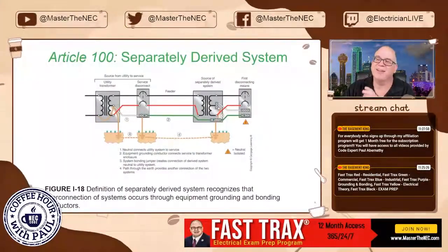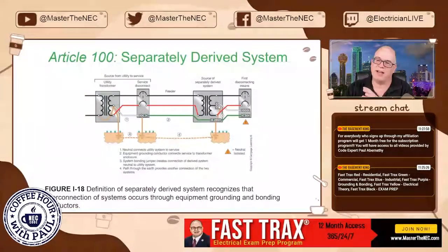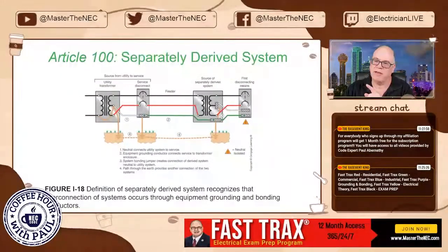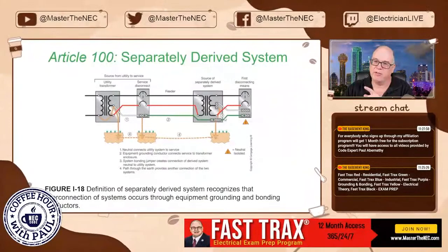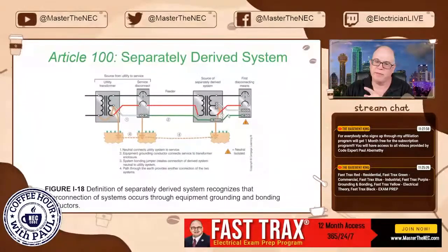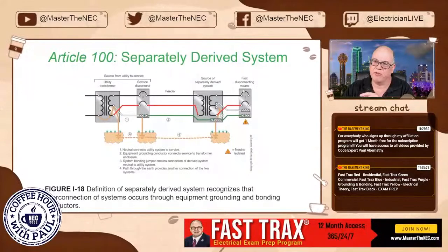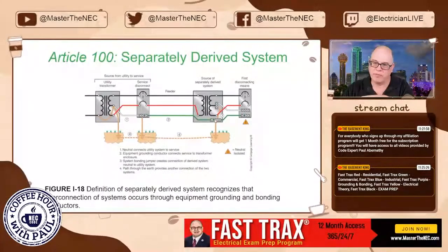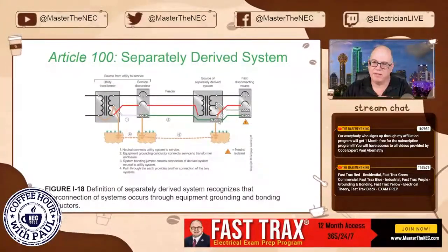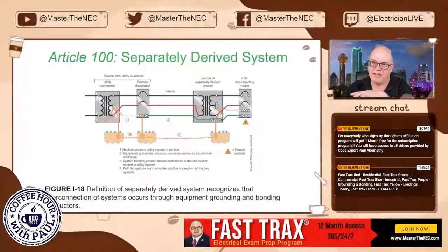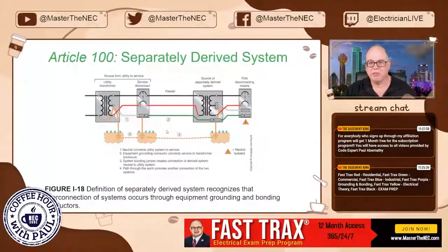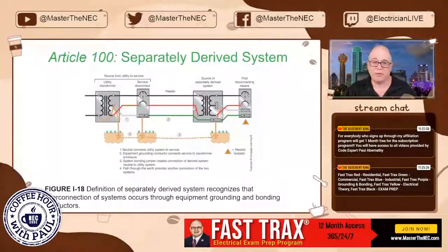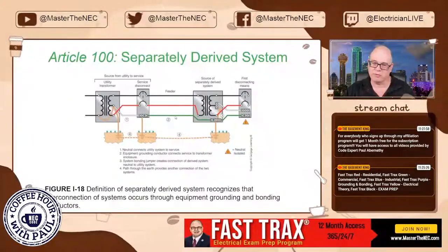All right. So here you see secondary side, and you've got your 4 conductors. Here you see the system bonding jumper right here. Here, right here is this conductor running up. There you go. And here's your first disconnecting means. And you see that they're isolated up here. So your system bonding jumper is done out here. Everything's done out here. And you've got your supply side bonding jumper run up here. Okay. So that's kind of a layout of how the separately derived system works in this. Transformers are separately derived systems except for autotransformers.